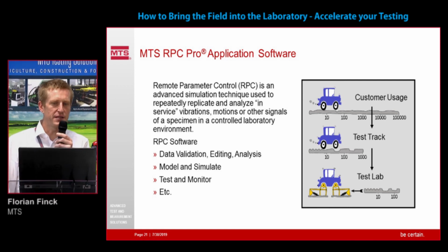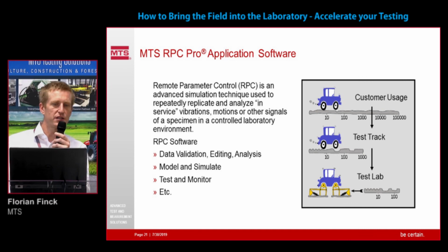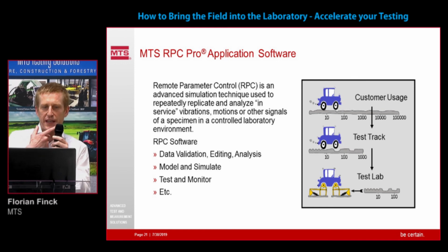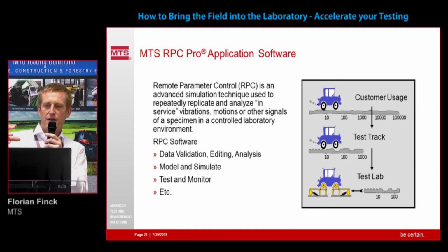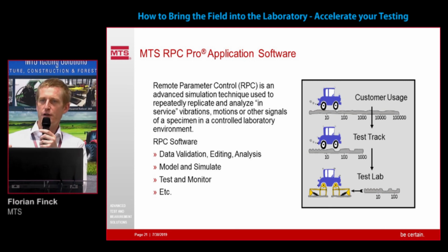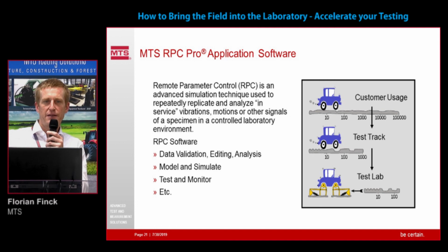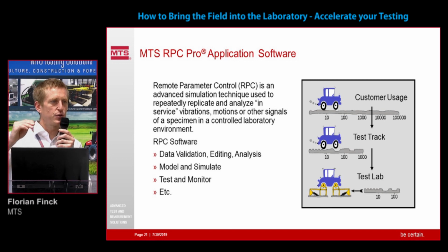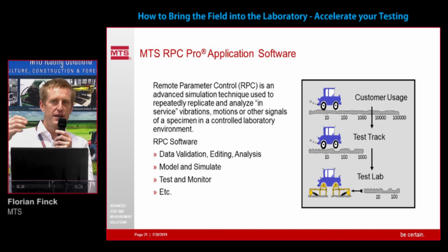For this, we use the RPC Pro software. RPC stands for Remote Parameter Control. And RPC originally is a control technique. So when you have the actuator controlled by a displacement or a force, but the signal you are trying to replicate is the acceleration on the vehicle or the force on a wheel force transducer, remote refers to not controlling the system to the sensor that's built into the actuator, but it's remote on your vehicle.